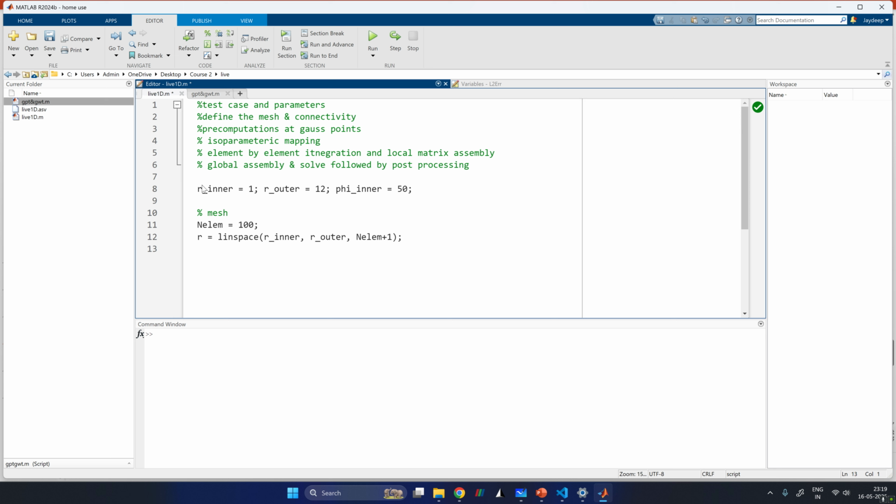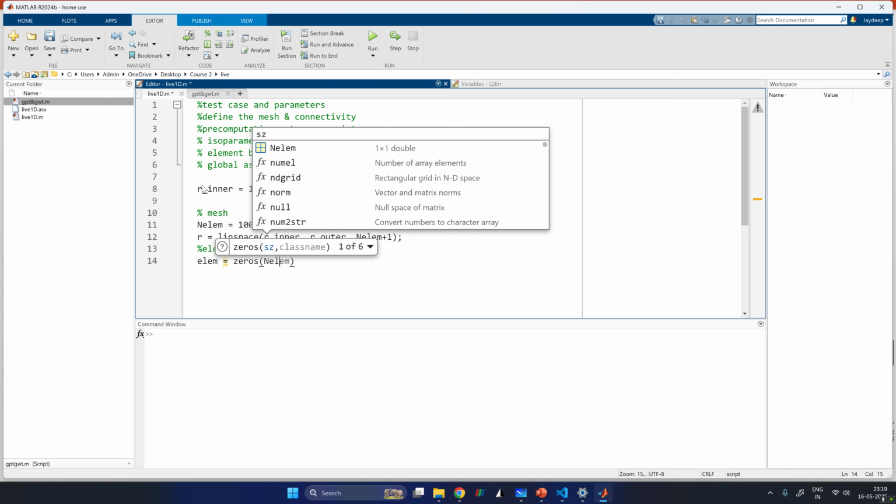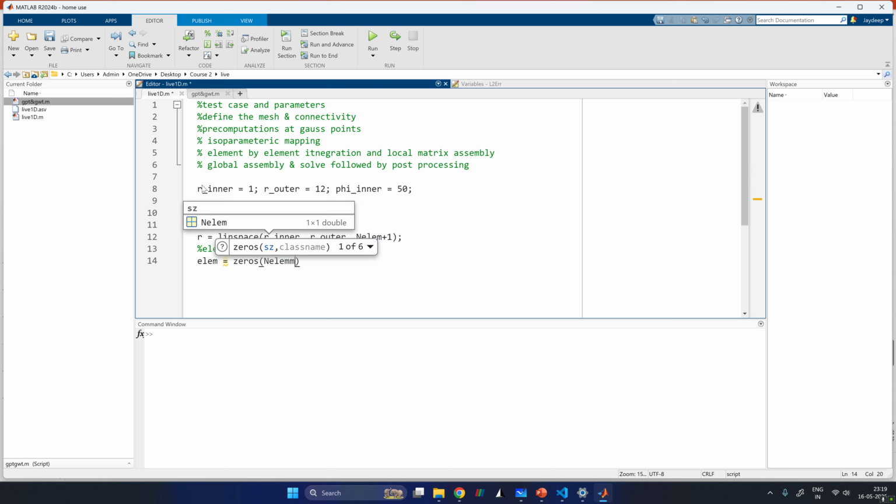So now let's build the element node connectivity. This is really important. In case of unstructured grids, this is a bit harder and needs more bookkeeping, but in this case this is very easy. So I'll just build this list here. I've initialized it as a parameter lm.